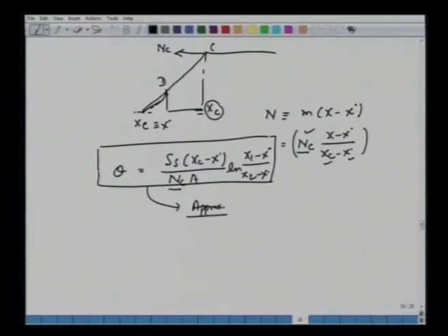Alright, so we have non-analytical expressions as well as numerical expressions to calculate the total time of drying here. Starting with this n versus x, n versus critical moisture content, if we identify all the points, constant rate, decreasing, then further decreasing till it is xc, one can start with the generic, very basic definition for rate of drying and see which range is constant. You can do it analytically, numerically, or you can make these approximations and do the numerical integration as well.